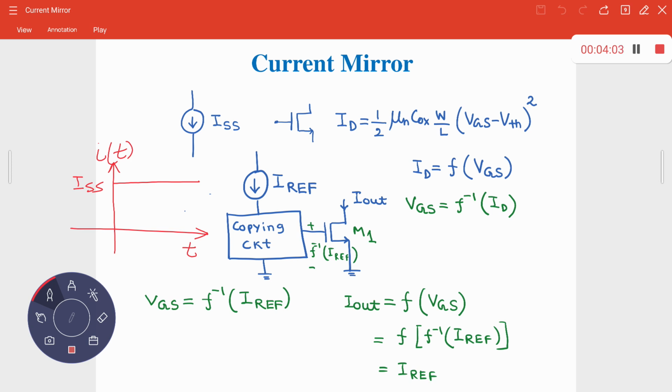And in a particular circuit, hopefully some of you attended the class last day, you have seen the differential amplifier: on one side you have 1, 2, 3, and so on, seven MOS devices in total for the design of this differential amplifier, with a current source load, along with a differential pair and a tail current. So you have seven MOS devices in a particular circuit. Typically in an integrated circuit, you can expect there are so many MOS devices.